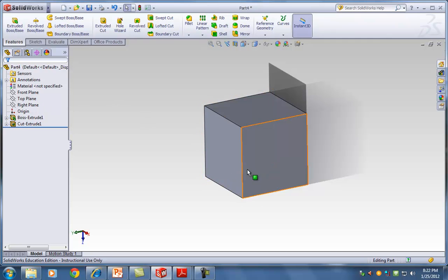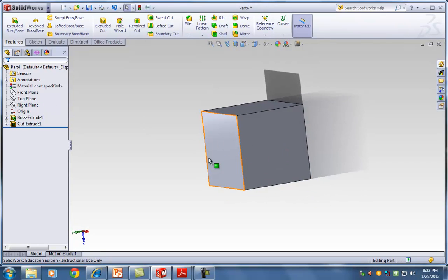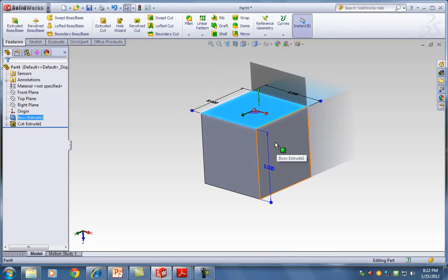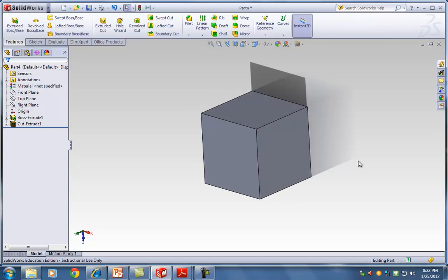It's very simple. If I want a plane to be located here in the center, all I have to do is just click on this surface and add a plane, and then offset it by 2.5. Right? Just like we did a second ago. We started from the front plane, we offset it by the radius. Same deal here. Okay? Now I'm going to show you a nice trick.